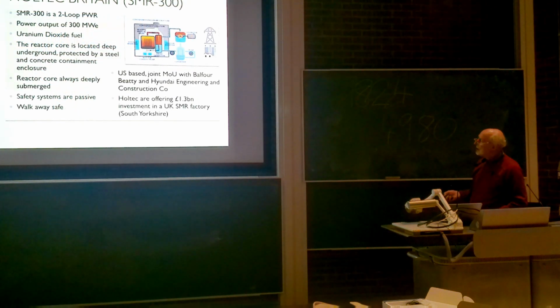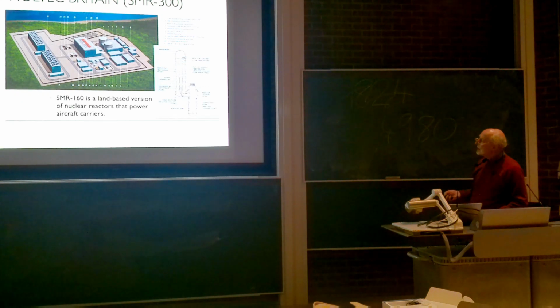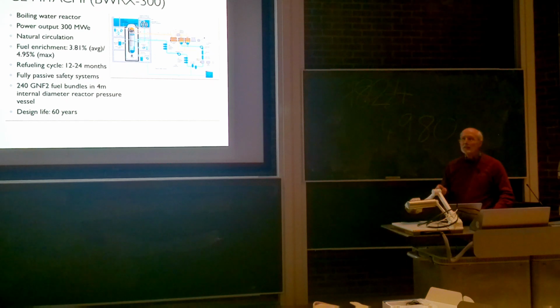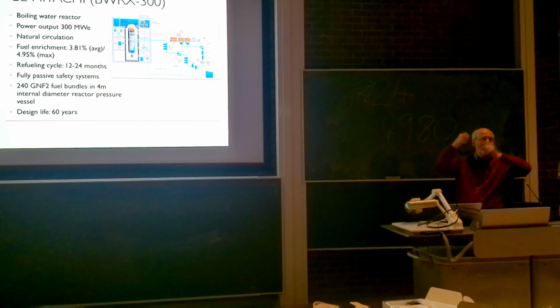And it's the same, therefore, with the boiling water reactor. Again, you need to either remove the whole pressure vessel or take the top off and then take out the core. Just as an aside, and I don't think it's classified in any way, but on submarines, they cut a hole in the top of the submarine and yank out the whole pressure vessel and replace it with another one.